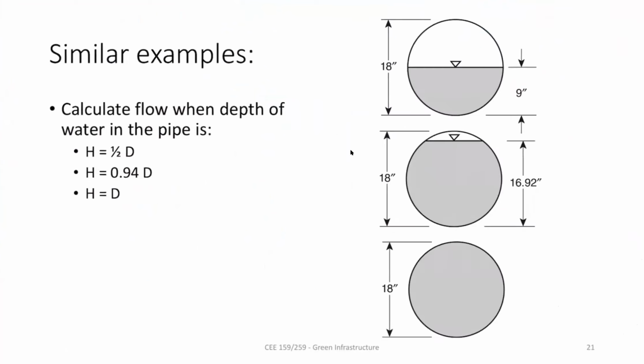So conceptually understand this: pressure depends on water height, because the height basically tells how much weight of water is above that point. Pressure varies with the depth of water. On the top surface there is no pressure, because there is no water. As you go down, there is more water above it, so that means pressure will increase.